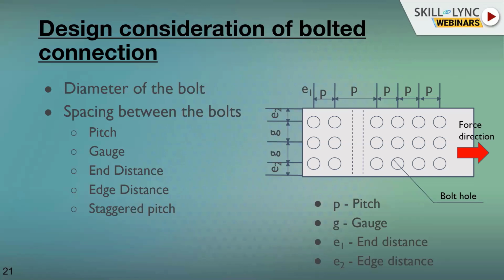One more thing is staggered pitch, in which the bolts are placed in a zigzag way. That can distribute the load faster and in a much better way, and is mainly provided for inclined members or members connected at a particular angle. Likewise, they can be given. Next, please.